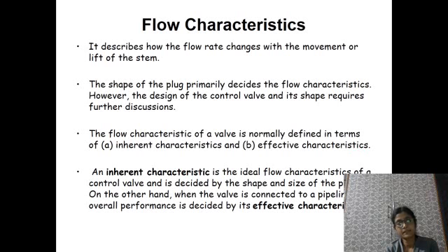So inherent characteristics is the ideal flow characteristics of that particular valve and is decided by the shape and size of the plug.